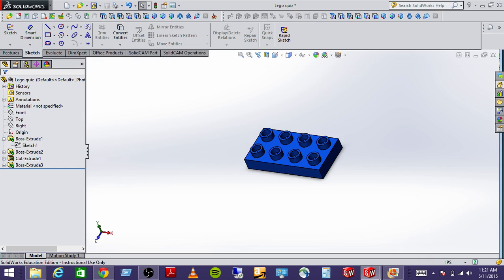On this unit, down here is a potentiometer, and that's a feedback mechanism for the motor controller. Well, when we originally built this about a month ago, we used a different potentiometer. It had a different size and shape. So we designed this block and all the little pieces that connect it and hold that potentiometer around that potentiometer. Then Professor Hodgkinson decided to change the potentiometer on me. So instead of deleting all that stuff, I suppressed it and then built new mounts and connectors and collars for this potentiometer.